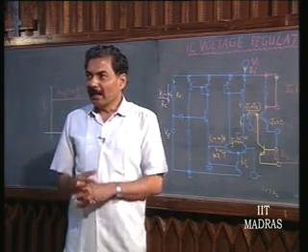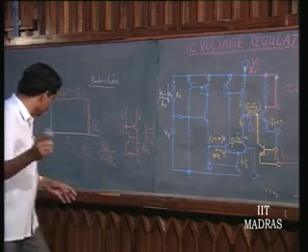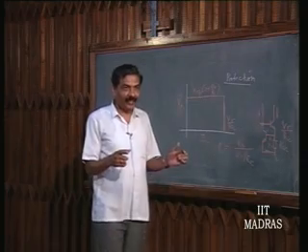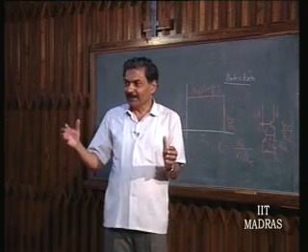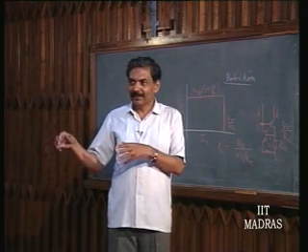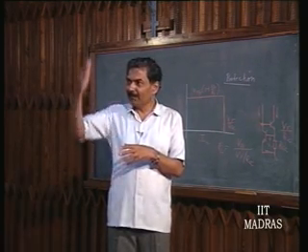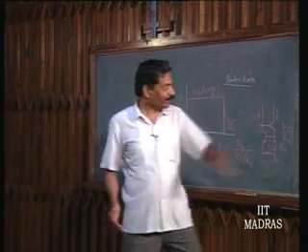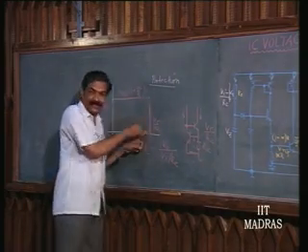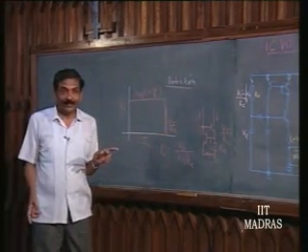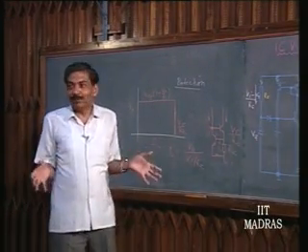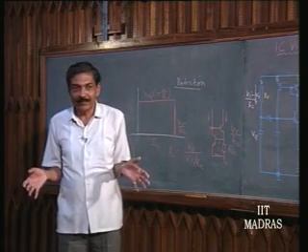You look at it, as I already told you earlier, the PD max is governed by Vi minus V naught into I naught max. Maximum current is flowing, but V naught can be anything now starting from this value down to 0. Let us say it is real short circuit, RL is real short circuit. That means V naught is 0. Then the entire input power is getting dissipated in the IC.